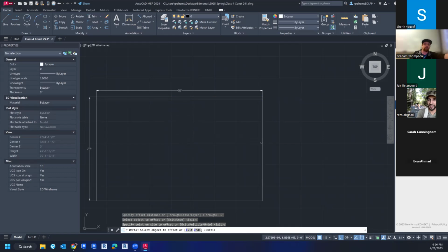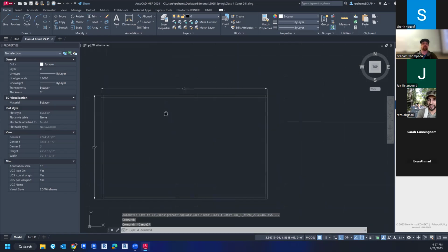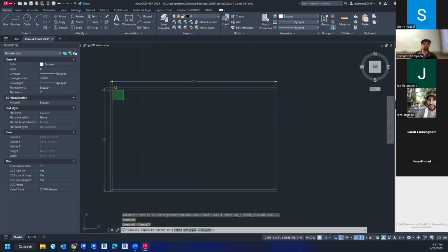You can go ahead and then just click the next item, right? The next outside wall, and click on the inside again. The bottom one, and click on the inside, and the left one. Okay. And then we're going to look at drawing this with a rectangle or a polyline and what advantages we can have when we don't have individual line segments. Okay, so right now, I'm going to just grab all of these inside lines and delete them.